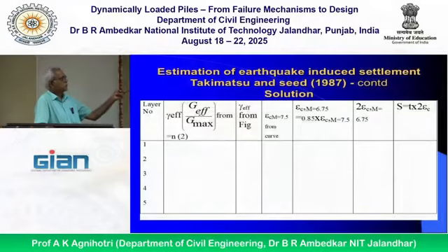So gamma effective from that figure, then epsilon C from the next set of curves corresponding to gamma, you can calculate epsilon C. Epsilon C for that will be for an earthquake of magnitude 7.5. Then epsilon C for our case magnitude, we will multiply it with 0.85.